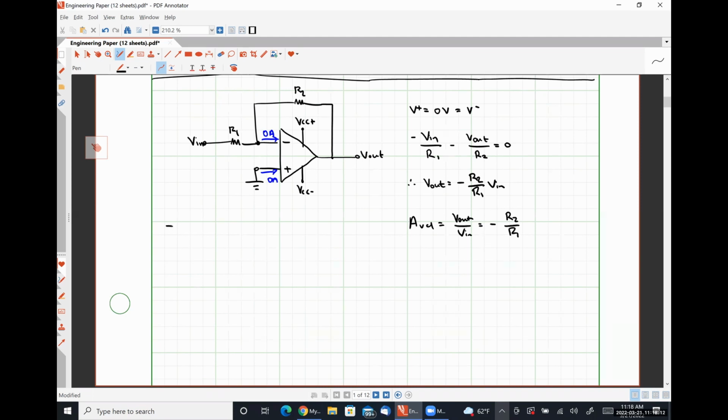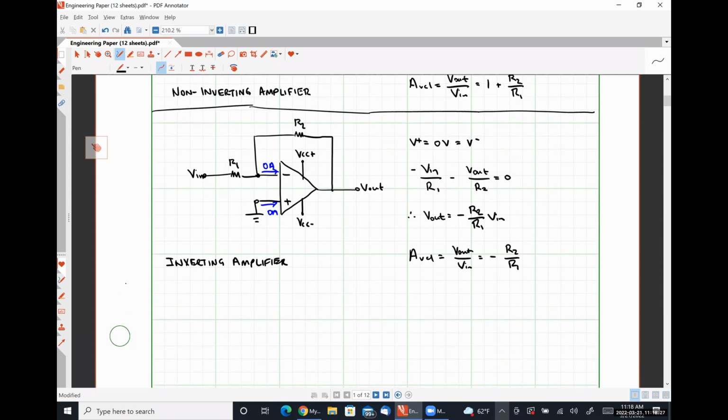This is an example of an inverting amplifier, where again, that name comes from two reasons, which are effectively the same. Our input signal is applied through our resistor network to our inverting input, and we can see that for a positive voltage Vn, our output will be a negative voltage. So we are inverting, or changing the polarity of, our signal.